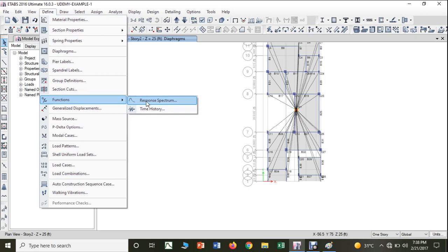So in this response spectrum method, we are going to consider that. We assume that our building or structure, which we are going to design for the dynamic analysis, is going to be subjected to an earthquake in the future. Therefore in IS 1893-2002, India has been classified into 4 zones, zone 1, zone 2, zone 3, zone 4, based on the frequency or repetition of earthquakes over a period of time. So we have to choose in what zone our building is present.